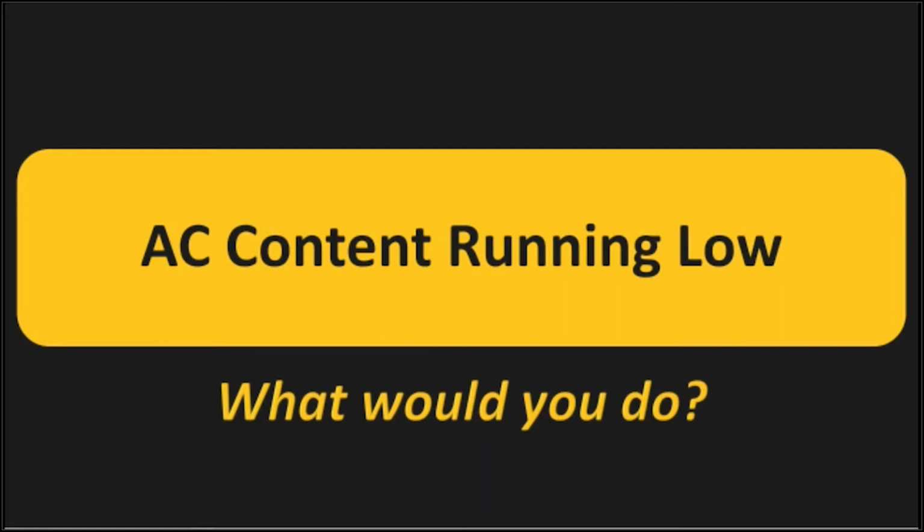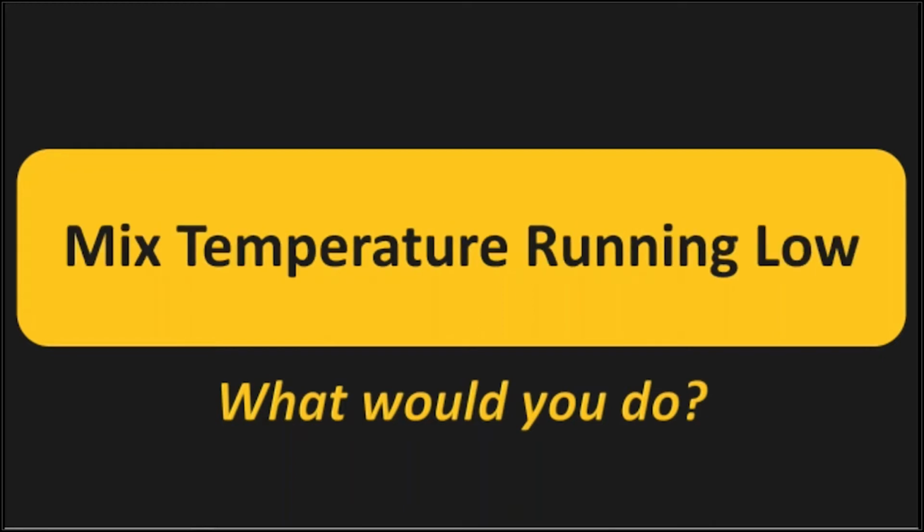Obviously, if the mix is running low, let me just go back to that slide real quick. We didn't talk about performance. If our mix is too low in the field, we're going to have a bigger challenge getting density. And there's a lot of work that's been done relating roadway density to actual field performance, so that's something we just don't want to give a pass.